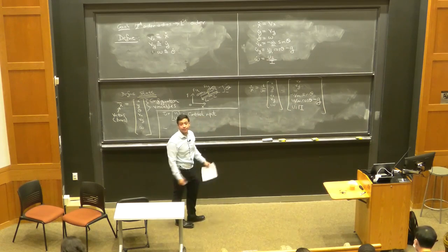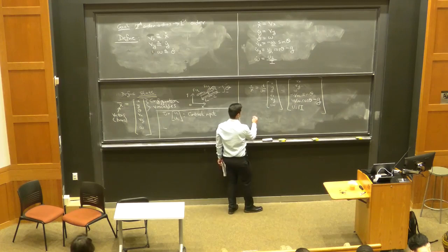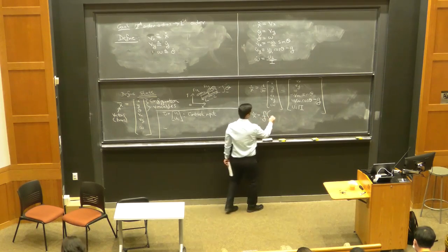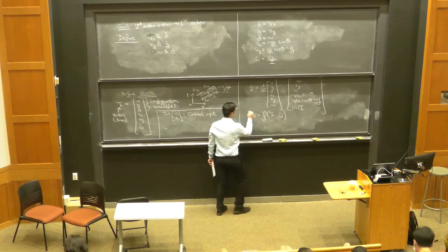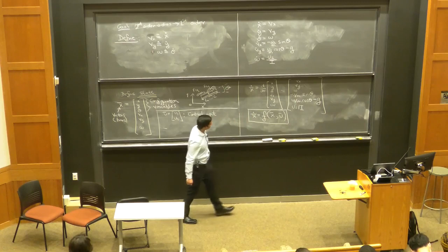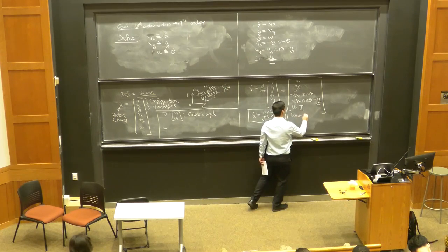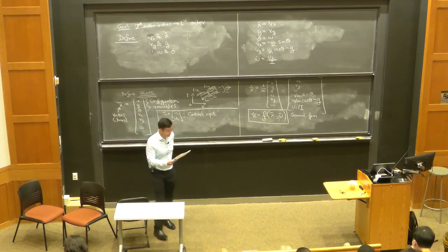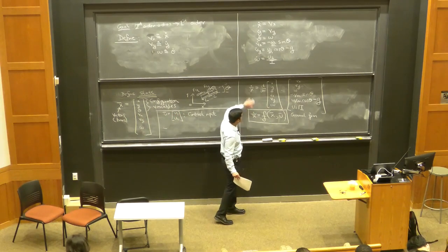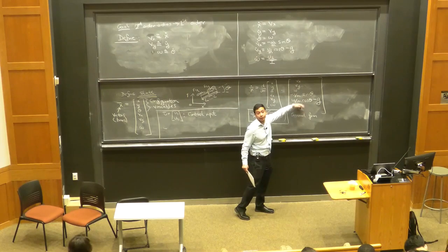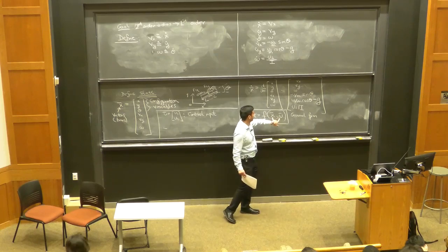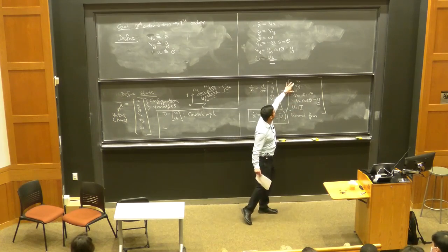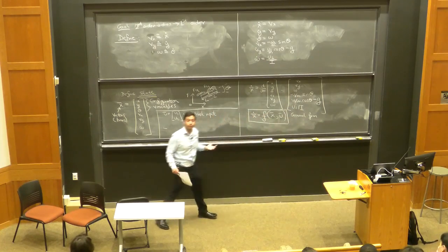Okay, so if we look at this system of first order equations, we see that it has the following form: x dot is some function, which we can call f, of x and u. This is going to be the general form of equations that describe the dynamics of our robotic systems. Maybe just convince yourself of this. Everything that appears on the right-hand side is purely a function of x and u. Every variable that appears here is some component either of the state or the control input vector that we've defined.